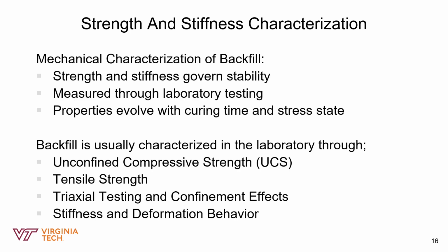You need to understand that these properties are not static. They evolve with curing time because of the cement content. And so a sample tested at 7 days behaves completely differently than that sample tested at maybe 14 or 28 days. So to capture the mechanical strength of backfill, usually we rely on laboratory tests, because in situ tests,